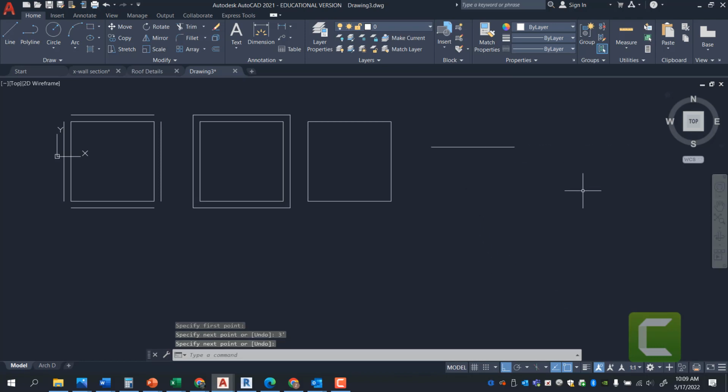The second drawing tool we learned was PL, which was polyline. Similar situation, you click into the model space, you drag your mouse, type in 3 feet, enter, and this is a polyline that has a dash through it and a line that has a dot.